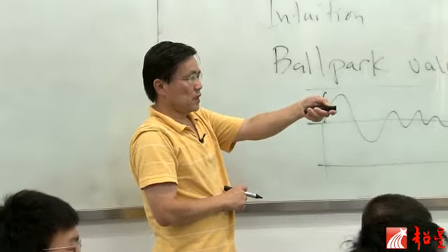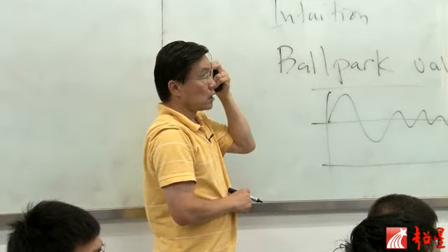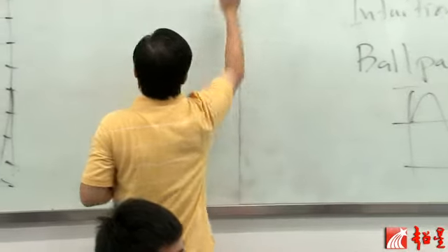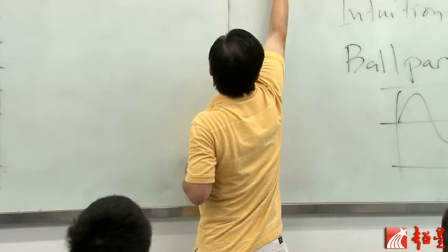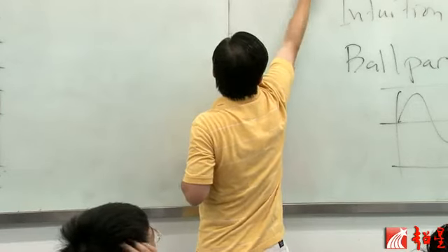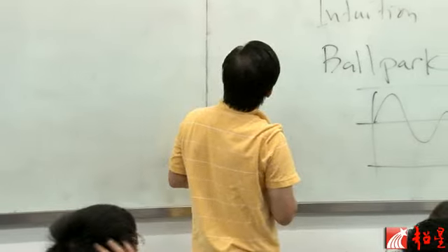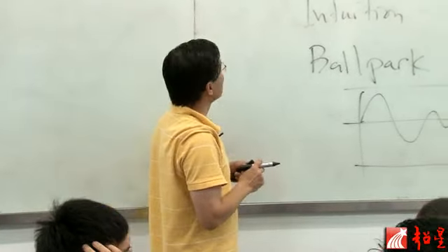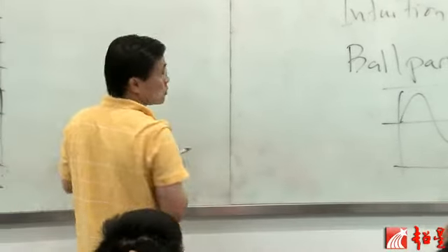And then the reflection coefficient at the load is 450 minus 150 divided by 600. So the load reflection coefficient is 450 minus 150 divided by 600, so it's positive 0.5. So those are the reflection coefficients.